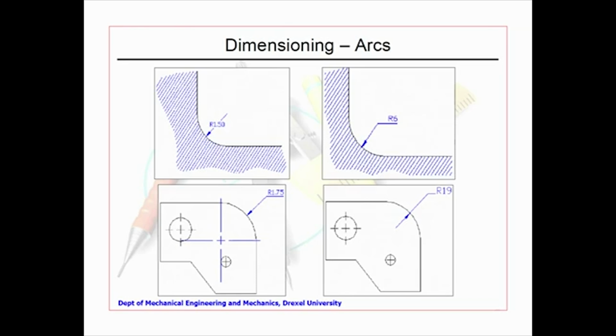Now, there are two other things here. There are two fillets here. This one is a fillet. Fillet is typically what you do for making sure that stress concentration does not occur. So, this could be part of a casting or it should be a part of some other thing, an internal bore. So, see where the thing is